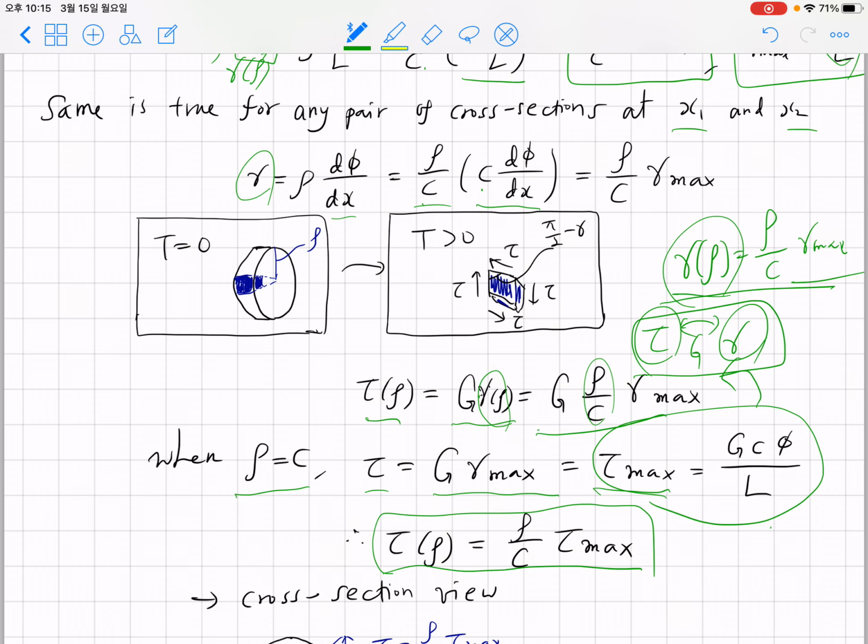However, in torsional loading, shear strain and shear stress are not uniform over the entire sample. Depending on the distance from the center, which is rho, you have different shear strain and different shear stress. That's the complexity we are adding in the torsional loading chapters.